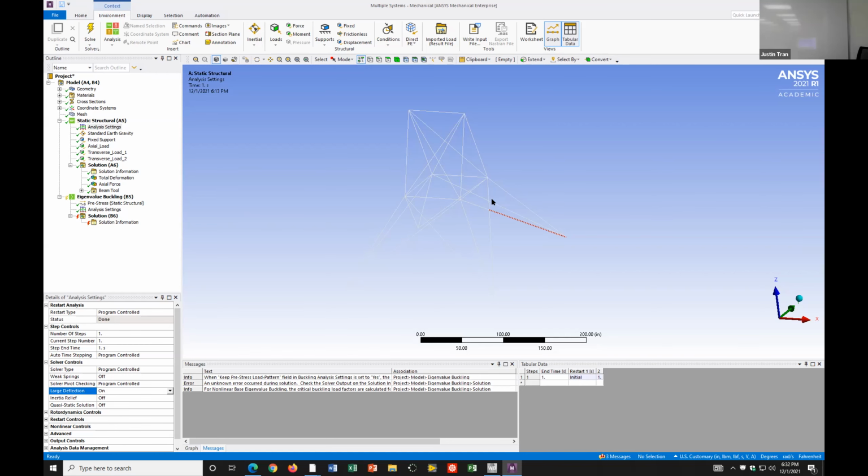Yeah, it's because those are the points, because buckling is defined when you apply compressive load and the bending stiffness essentially goes down to 0 or goes down to a very small point. Compression, right? Yeah, it has to be in compression. You have to do it separately. But I saw on the legs before. Yeah, it should be in the legs. All right. So yeah, there you go. You got one here. So check the higher ones now.